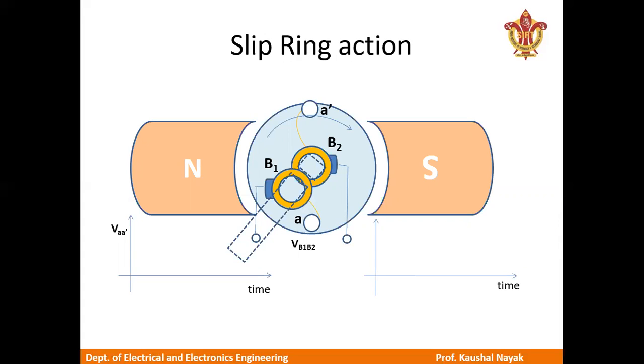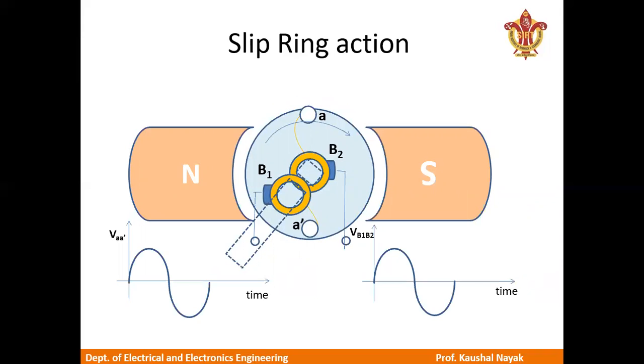Generally, the slip rings are directly connected with the armature terminals, and together they become the rotating path along with the coupled shaft. And at any moment, whatever voltage waveform is generated across the coil is also obtained across the brush.